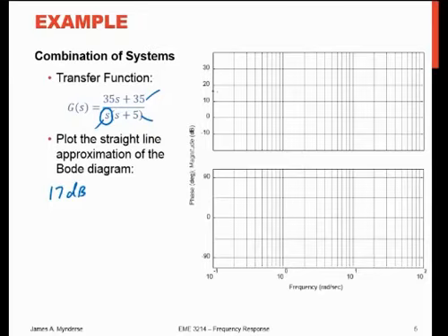Now, with that pole at the 0, what's the steady state gain? Well, there really isn't any, because if we look at this transfer function as s goes to 0, the denominator just goes to infinity, and that's really what happens with that integrator at the pole. If you give it a constant input, the output just grows and grows and grows. It's 1 over s. It just integrates.